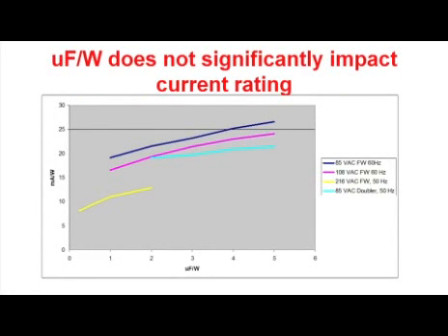The second chart takes our normalized capacitance for output power and looks at how much ripple current is in the capacitor. What we've done here is we've shown a variation of about 5 to 1 in the capacitance on the power supply and plotted on the left side the ripple current. You can see that the value of the capacitance doesn't have a significant impact on the ripple current. That's because the current in the capacitor is pretty much going straight to the power supply during most of the cycle. You just encounter a small charging current, and that's the only thing that really varies.